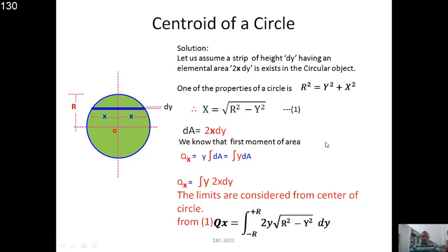For the integral or first principle method, the centroid can be found by using a smaller strip or differential elemental area. That means a very small area is represented as a strip or a thin line. The entire area is divided into these differential elemental areas, and for that we make an equation of a strip, and we apply the boundary conditions from its lower to the higher limits. After that we get the integration. For that example we took a rectangle, an isosceles triangle and a circle.